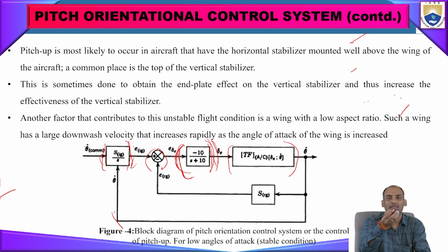Cm alpha, that stability derivative solution is there, no? Stability derivatives will always be in differential form. Whenever we want to solve a differential equation, we use the Laplace operator s. With the Laplace operator, whatever function we give to the integrator will be converted into the frequency response.